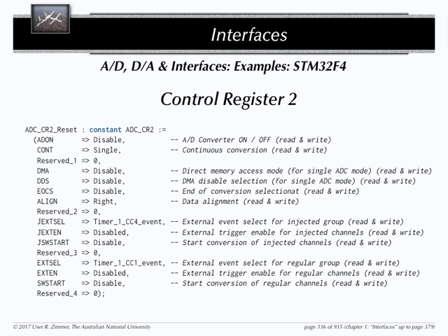Usually for comfort, you define on high level also what my initial state, the reset state of this register is. Can come in handy on your high level programming environment that you know what to expect to be in this register. If you want to start from the reset value and then manipulate it, you can just copy that in here. Because this is high level programming, you can take local copies. You can take a copy of my control registers. Nobody stops you from that. As a matter of fact, you will need to take copies of your control registers quite often.